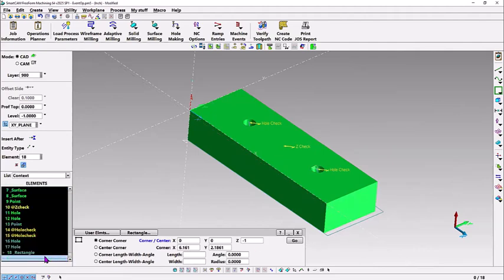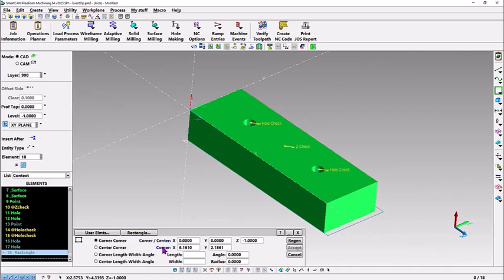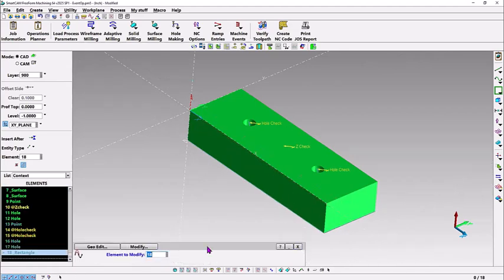But if we look, the rectangles in the past have consisted of 4 lines. So now I need to edit this rectangle. In order to do that, in the past, I would have to edit all 4 lines, both the X and Y, all 4 lines. But now all I have to do is right-click, container, and then recall this. And then I can snap the corner to where it's supposed to be, regen it, and then accept it. And it's just like a process container.